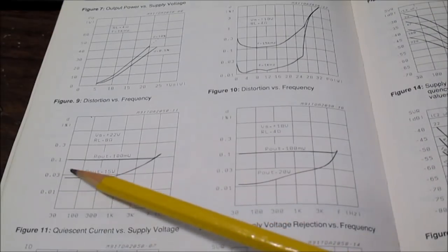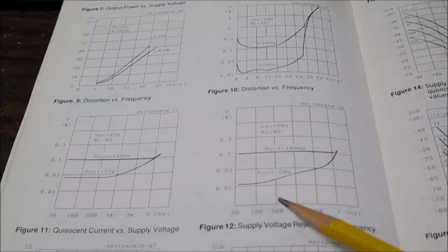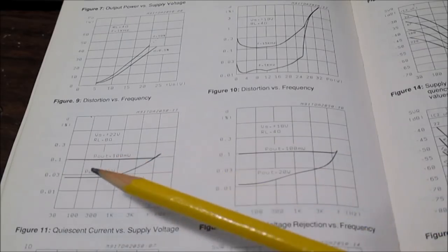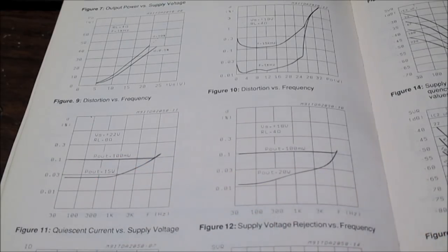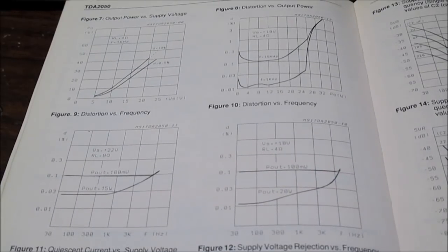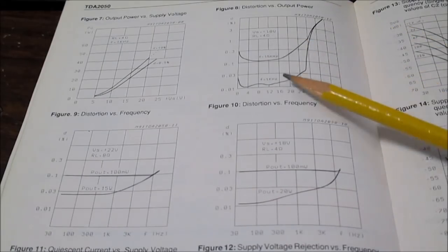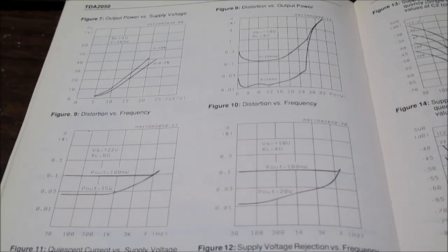This datasheet also shows distortion versus frequency, and you can see the amplifier is doing pretty good here. Now, it depends on your circuit layout how it's actually going to perform. If you have a very bad layout in your circuit, you're not using the proper star grounding, you may not be able to reach these numbers. And in some cases you can actually beat these numbers because a very good layout, better than what they used to test this chip, you can actually beat those numbers.